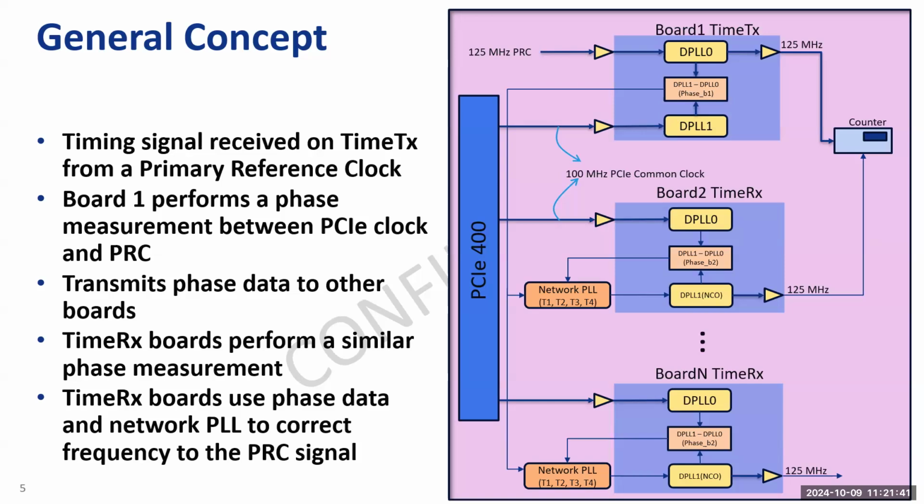There have been a few things that were glossed over here. So maybe you can comment, what are some of the challenges? Because with PCIe clock, especially in common clock mode, a lot of these systems are running with spread spectrum clock. And so how do you measure phase of a clock that is now being spread spectrum manipulated? How do you measure that to get a meaningful measurement between two boards? You didn't really comment on that.